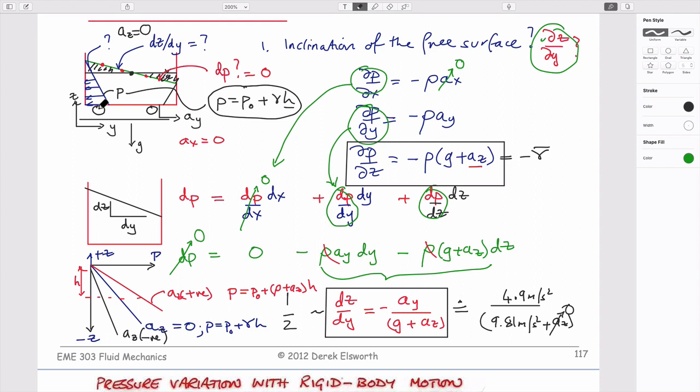And the pressure distributions, if it's not accelerating in the z direction, will be just the same as if it's in a static pool. It'll just be that it's a smaller force at the front because this triangular distribution only starts at the free surface and then goes down linearly at this rate. And at the back it goes down from a higher level.